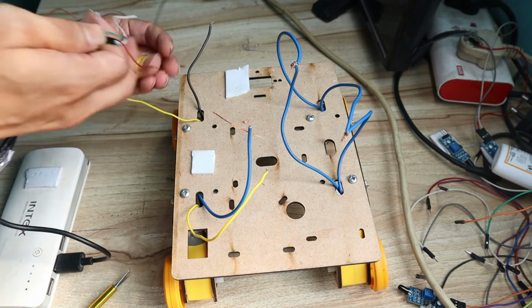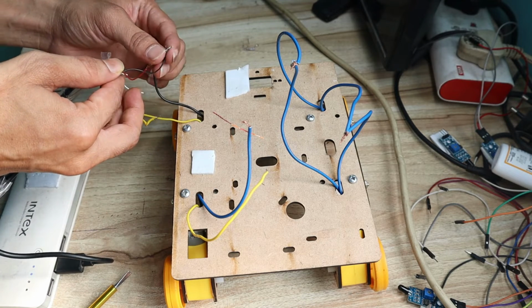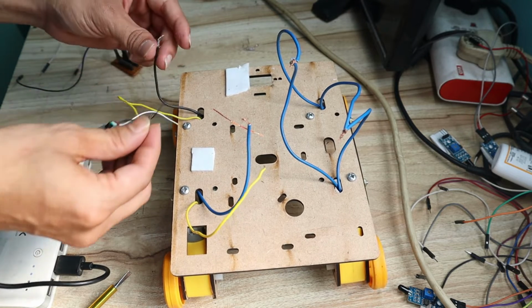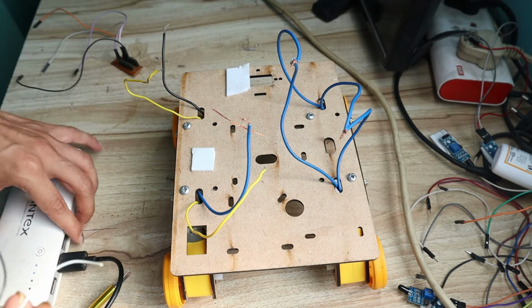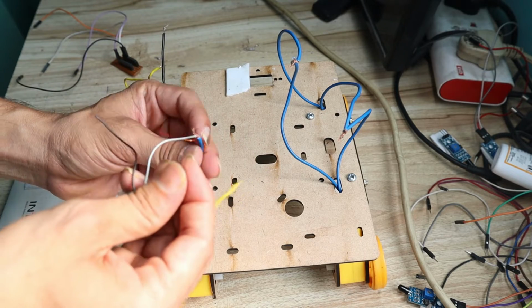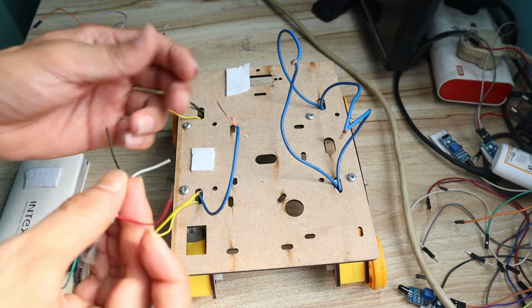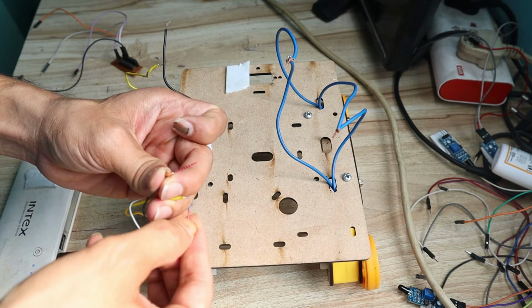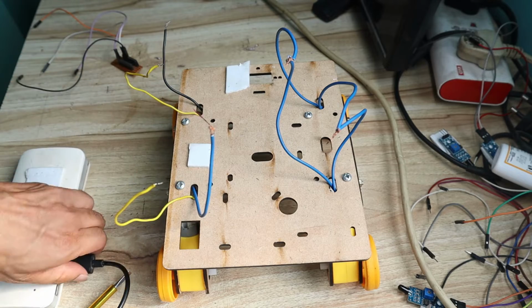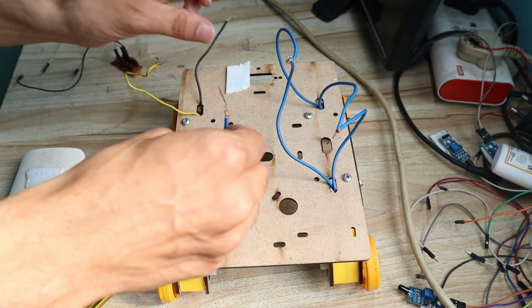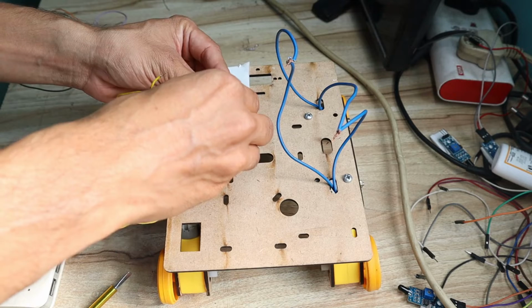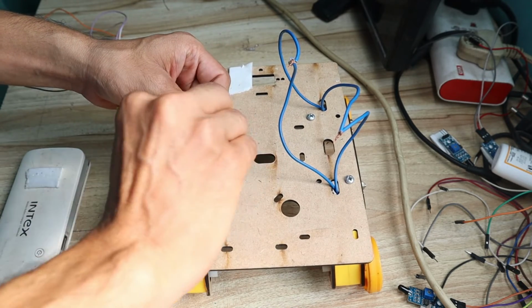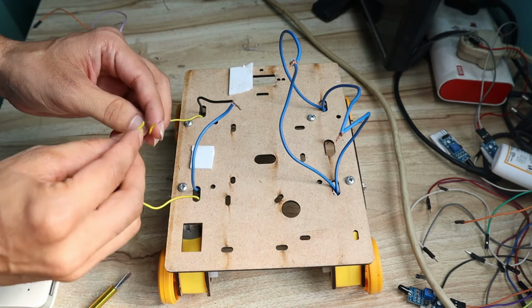So again from the power supply I will take random two pins and connect here. Okay, now I can see my motor is rotating in anti-clockwise direction. For the other motor I will again check the direction. So this is also anti-clockwise. Okay, so ultimately I found out these two pins are the negative pins. I will short them again here. And these two pins for these two motors.